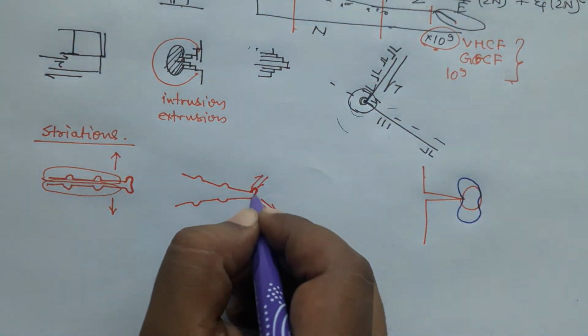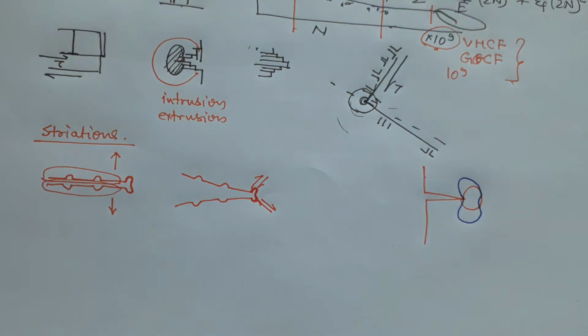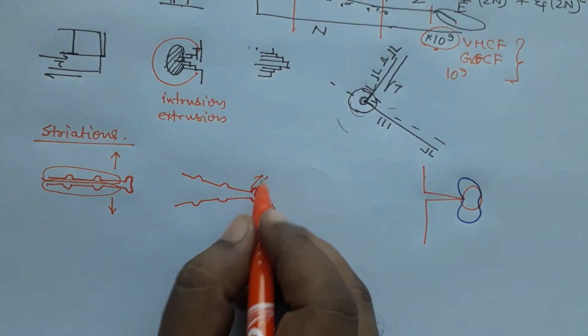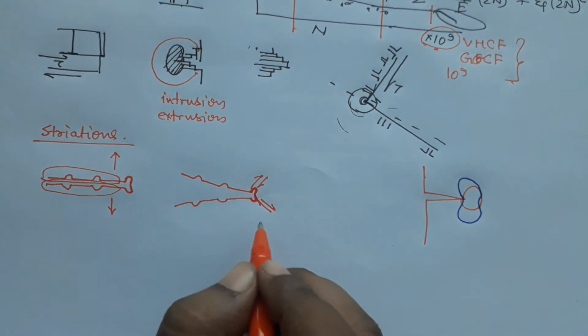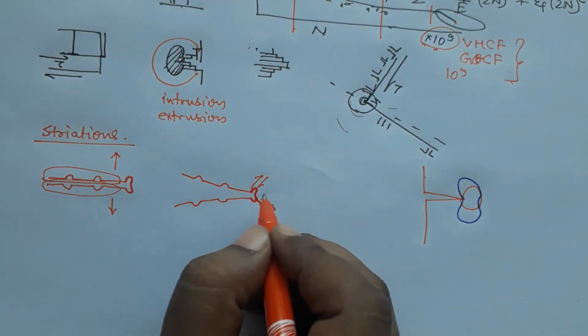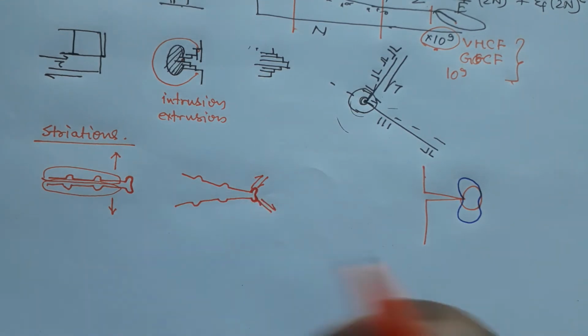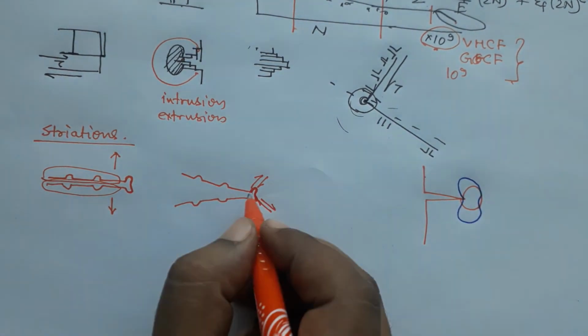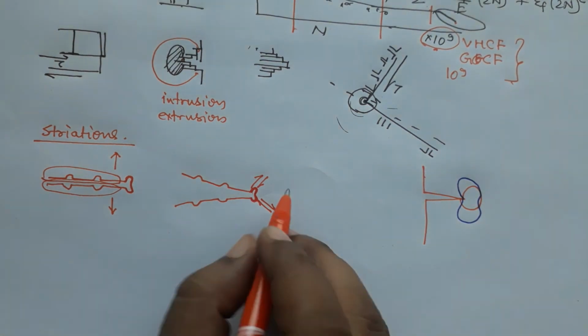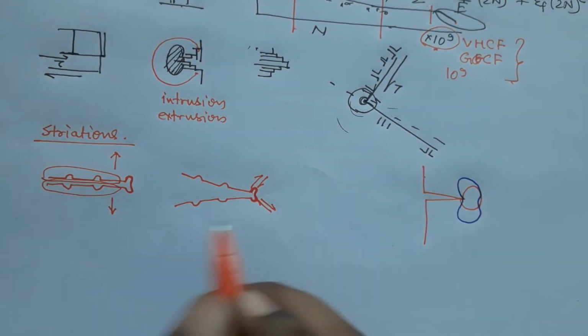So that kind of shape also is formed here because of shearing, and the material is deforming in that direction. Because of this there can be crack growth if the stress is higher than what the material can take, or the strain is higher than what the material can take, so the crack will grow, or not, if the stress is not higher or the damage is not higher.